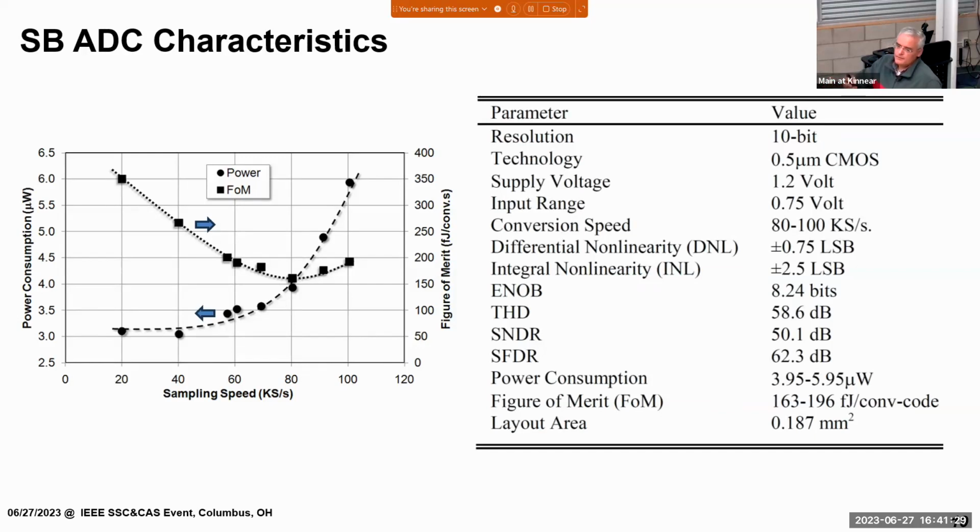Yeah. Typically, what they report in image sensor specs is measured in the dark. If you report in the dark, your ADC is going to consume less. Your analog signal chain is going to consume less because they are not amplifying the signals. So as a result, you end up with lower power consumption if you report it in the dark. If you report it in room lighting or outside lighting, your power is going to increase. And image sensor companies do that too.